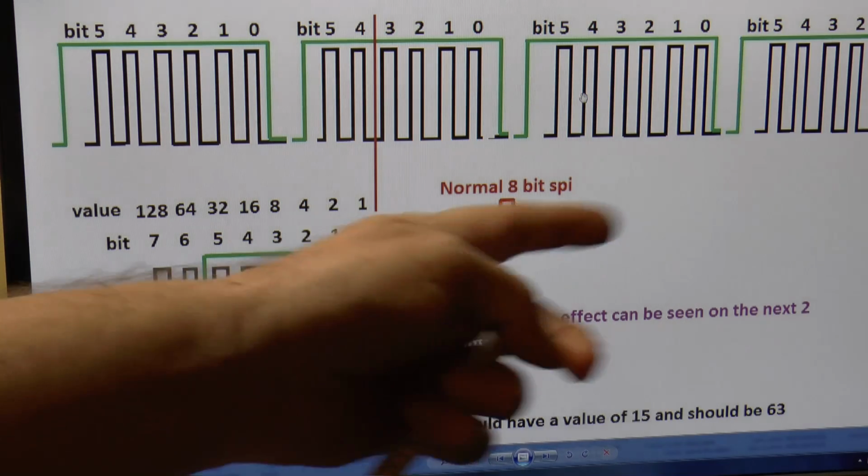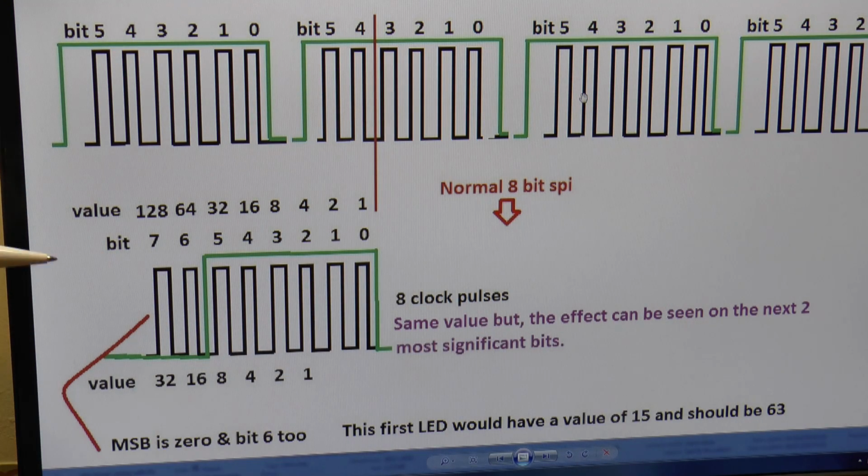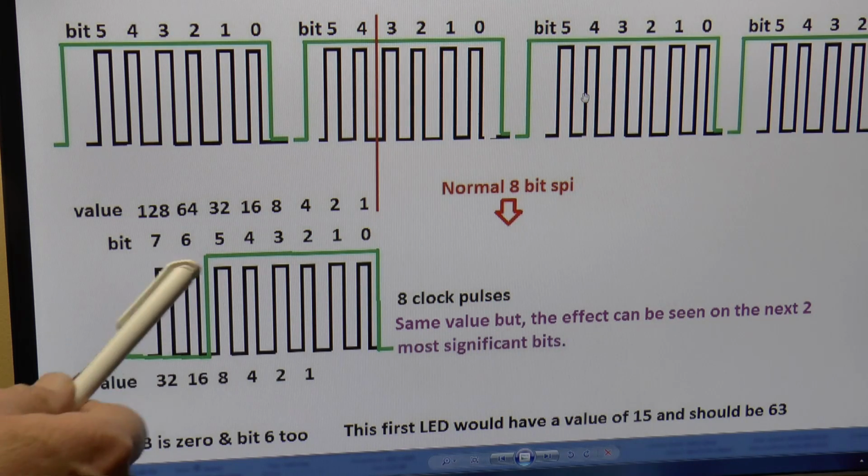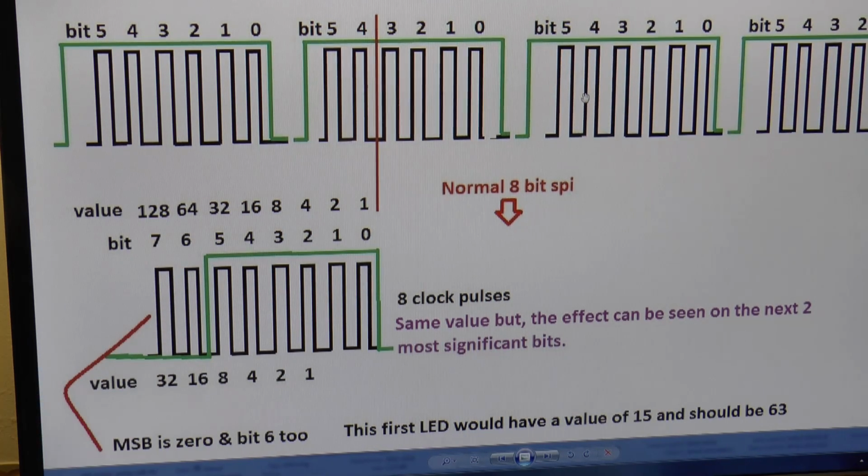And that's going to keep on happening. So the chip's going to look for 6 plus 6 plus 6 plus 6. If you keep on running in 8, 2 bits of data are going to be missing somewhere. And what happens, you just get random patterns on the matrix and not the particular LEDs you want lit.